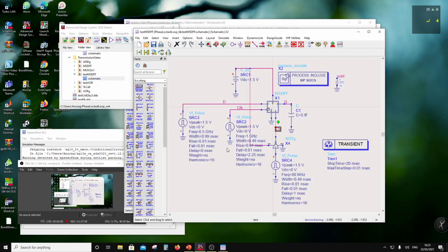We introduced a clock with a certain delay, and in between that delay, we introduced here the reset, right? So only thing is that the reset is going to be even much larger now. So what I'm going to do is I'm going to copy this one. Okay, so this is being driven at 1 gigahertz, but I'm going to drive it at 100 megahertz, right? So that's what I'm doing.